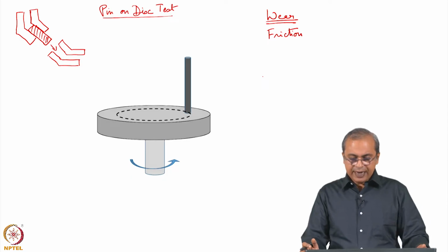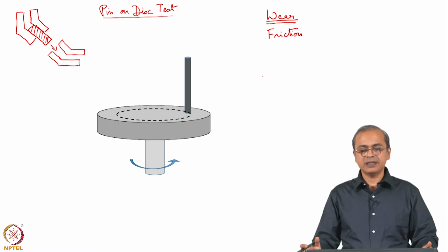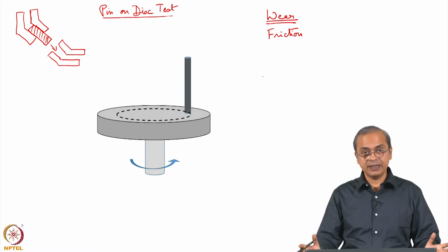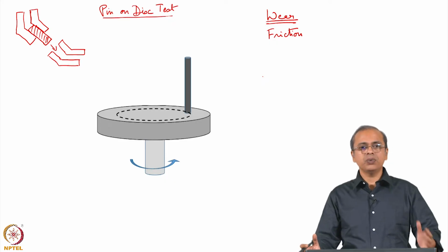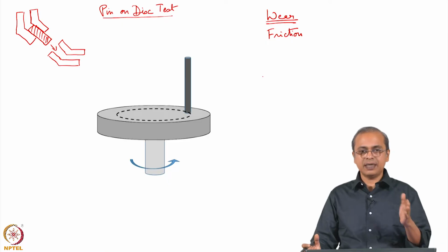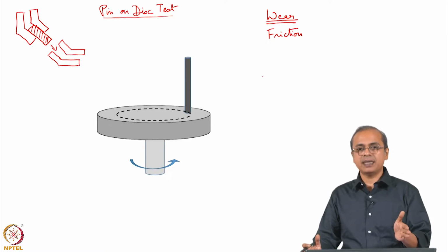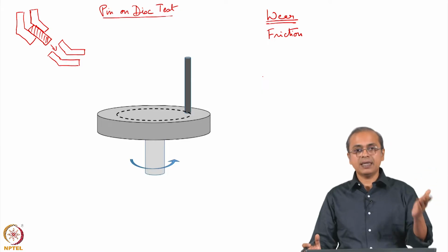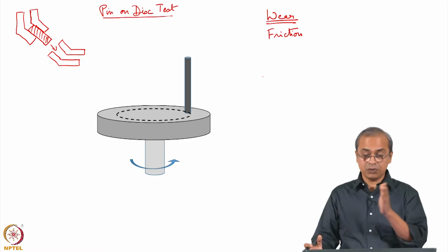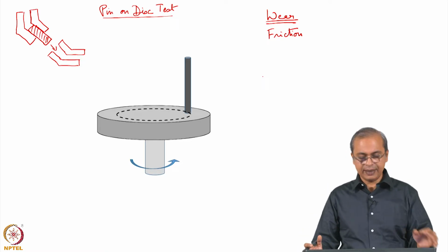So, to do the wear test, basically you have to create the same situation of friction. You have to see how that sample behaves once it is subject to friction, and you have to do this in some kind of a controlled manner. That is basically what a test is, right. So, you have to set it up so that you can test one sample, and then test some modification of that sample or some other sample, and then compare results. So, that is the whole idea: the test should be reproducible. Those conditions should be reproducible, and there are some defined conditions for it.